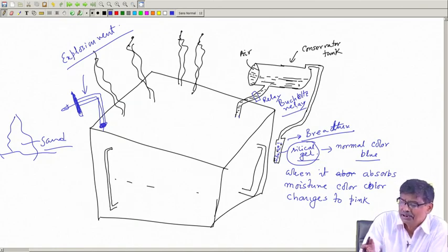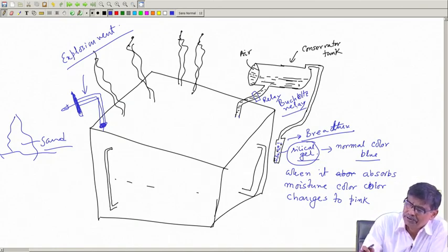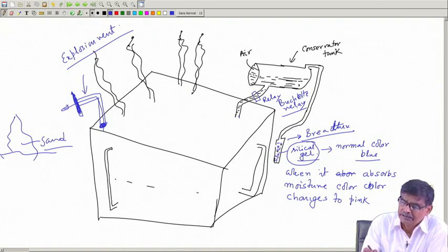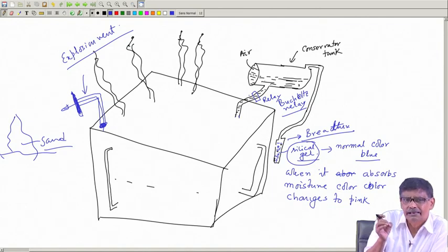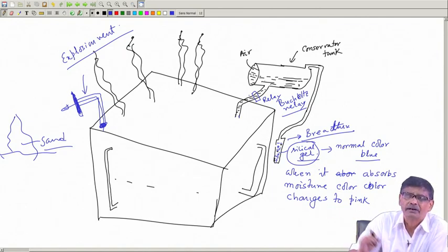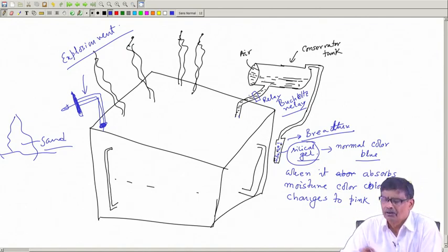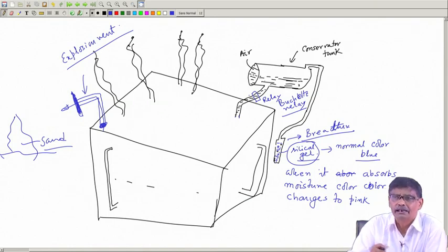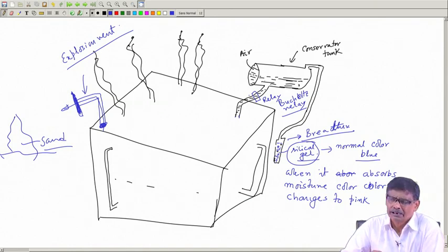When oil is heated, oil will push out, density will fall, there will be some floats inside, they will move. Through that mechanism, you can initiate some operation or it can give you some alarm, that things are not good for the transformer, oil is almost vaporized here.